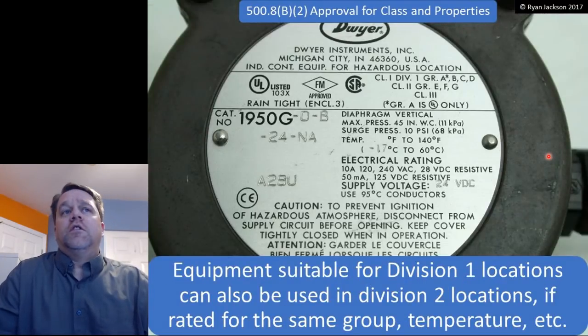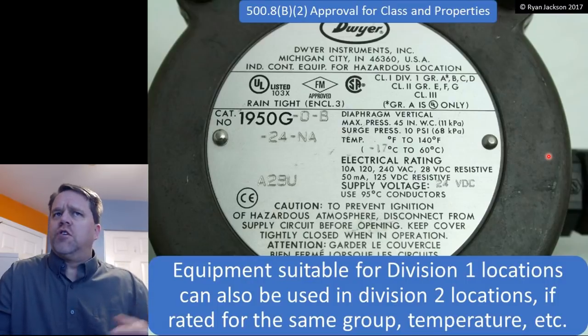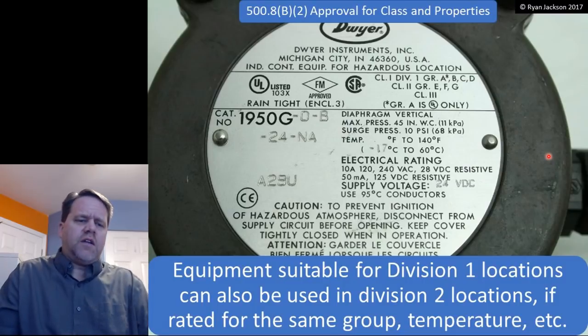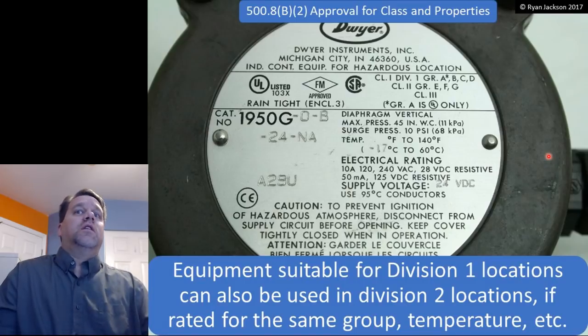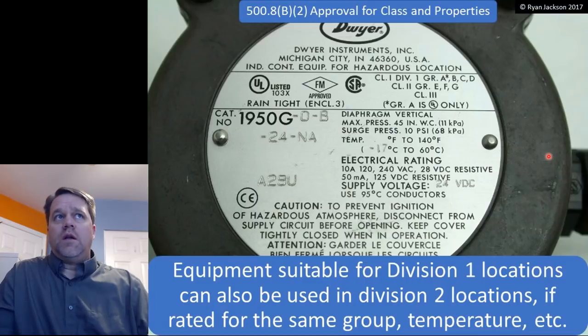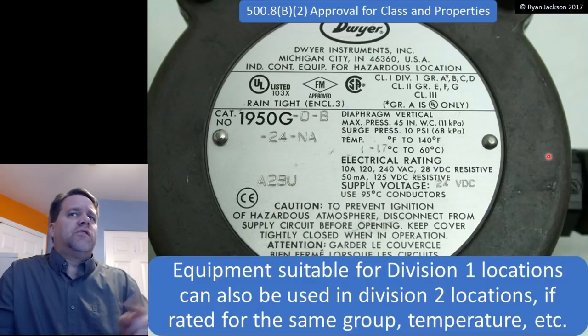Equipment that's suitable for a Division 1 location can also be used in a Division 2 location if it's rated for the same group, temperature, etc. That makes sense, right? A Class 1 Division 1 is much more hazardous than a Class 1 Division 2. So if it's rated for a Division 1, then I can use it in a Division 2. Now, we have to be careful here. Equipment rated for Class 2 can't be used in Class 1.